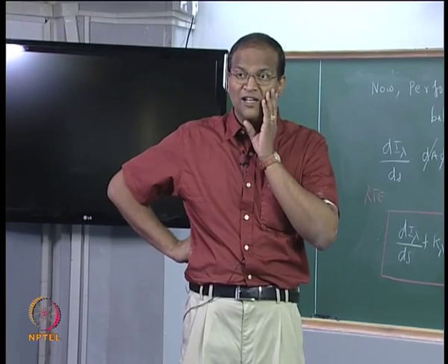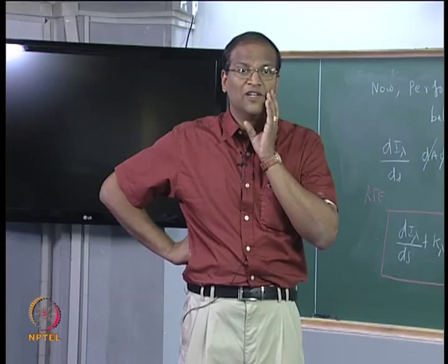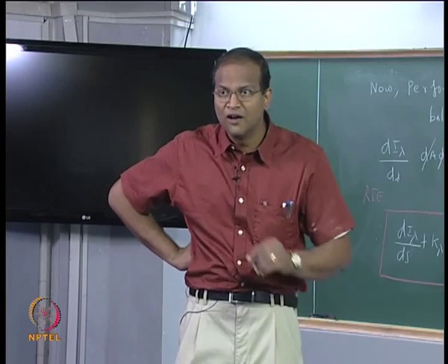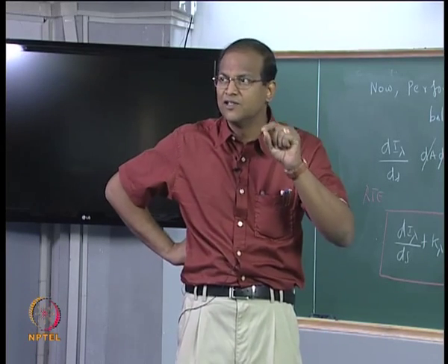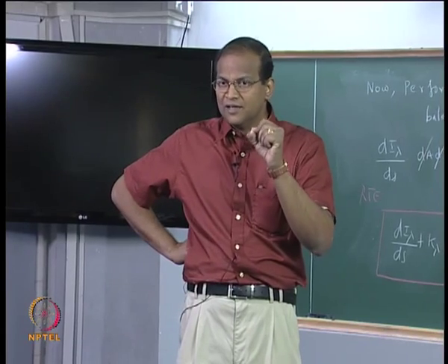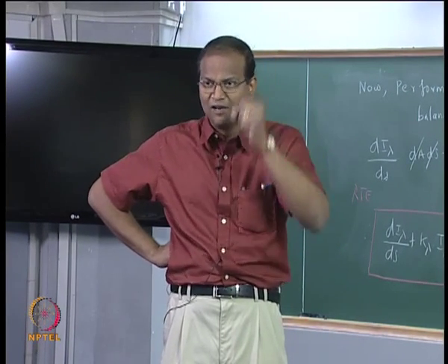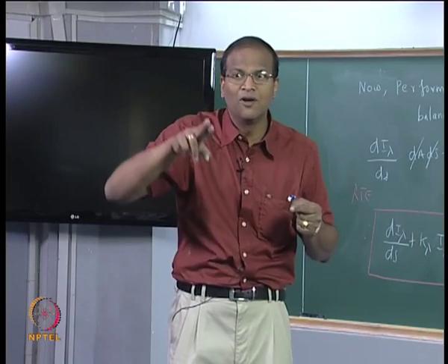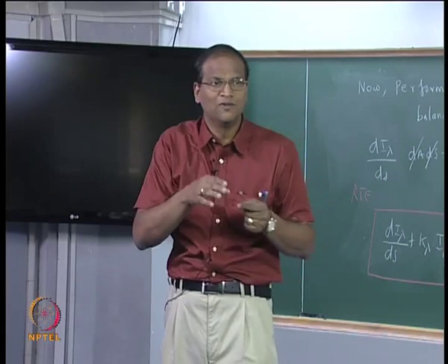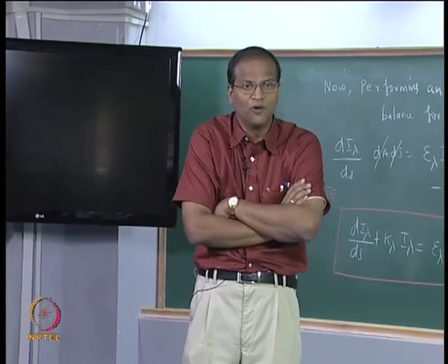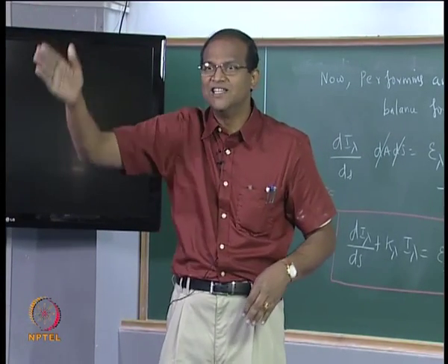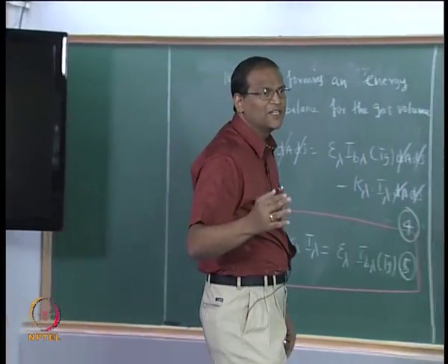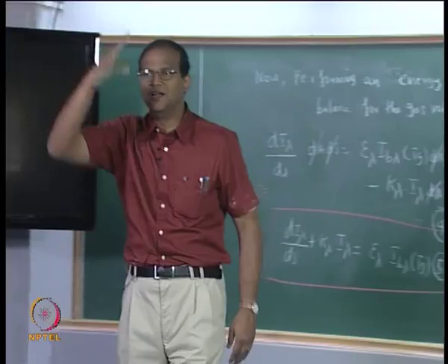Suppose we consider a 3 surface enclosure in which the temperature of each surface is varying with respect to x, and I can't use the uniform radiosity assumption. Then I have to divide each surface into subparts, and J1 itself will have several parts. Therefore, instead of summation I have to use an integral. The radiosity equation, where J equals epsilon sigma T to the power of 4 plus (1 minus epsilon) times sigma F_ij J_j, will become an integral. So the radiosity equations by themselves are integral equations.